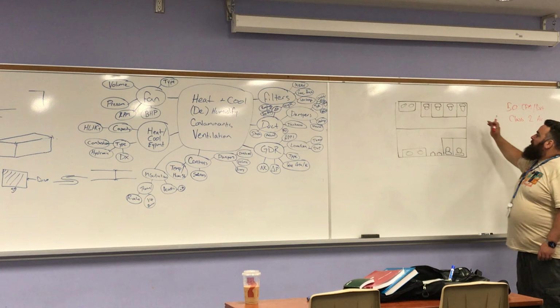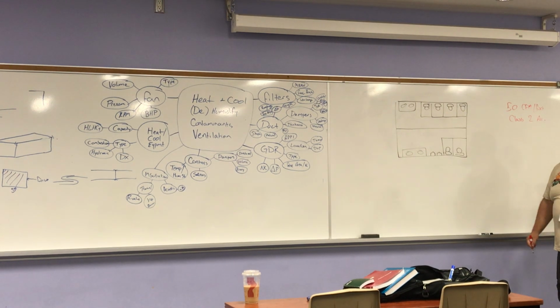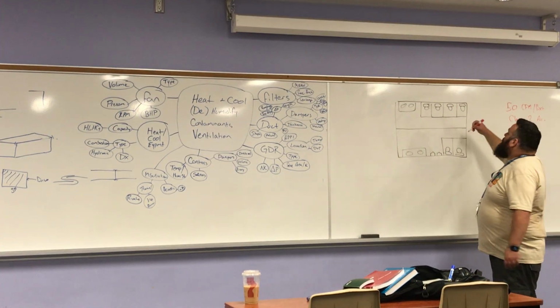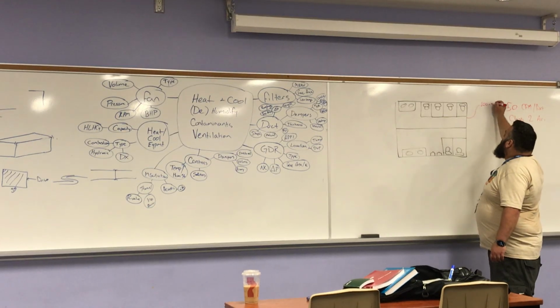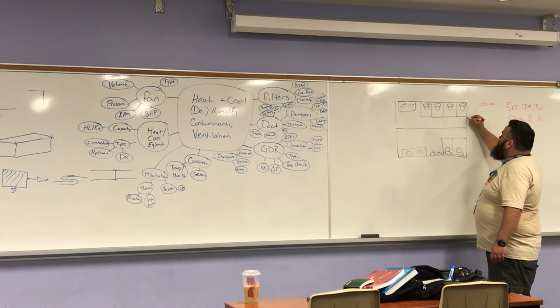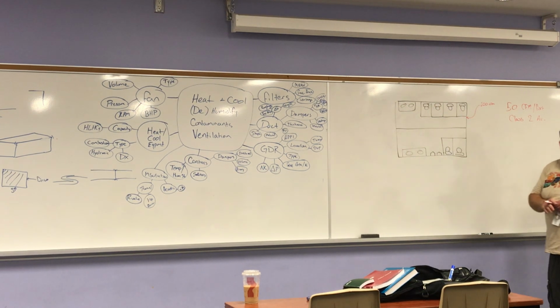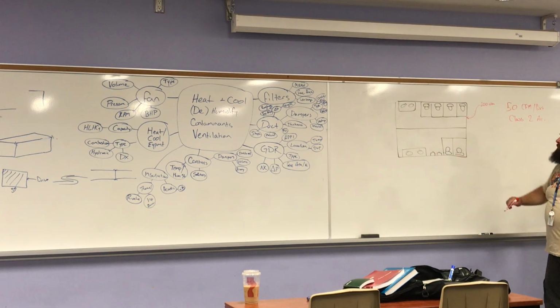How many CFM do I need in the women's? 200. 200? How'd you get that? Just multiplying the fixtures by 50. Yeah, we had 4 fixtures. We weren't concerned with the labs, so we need 200 CFM. Okay. For the men's, same. Never mind, same. 4 fixtures. 2 of them are urinals, 2 of them are water closets.